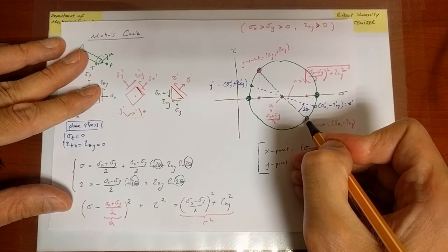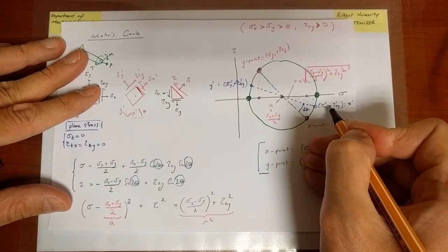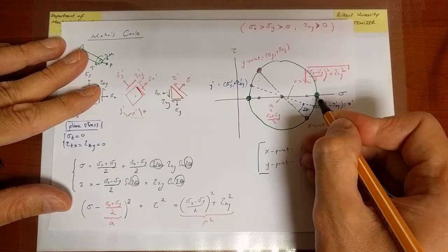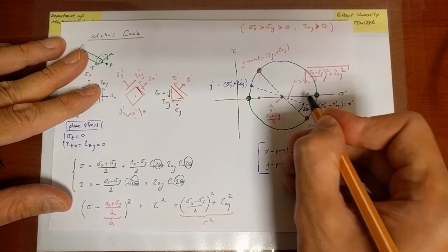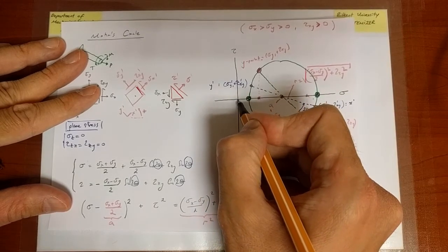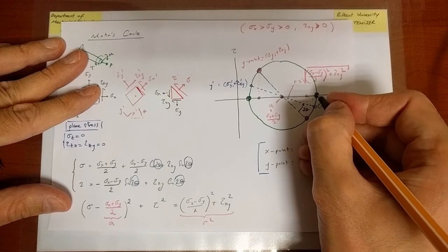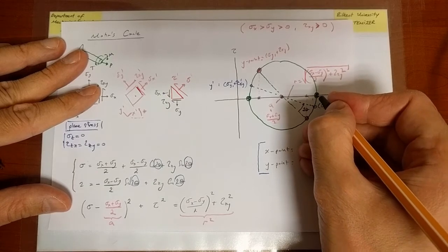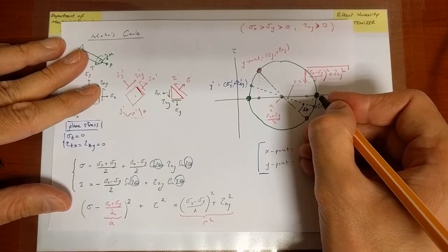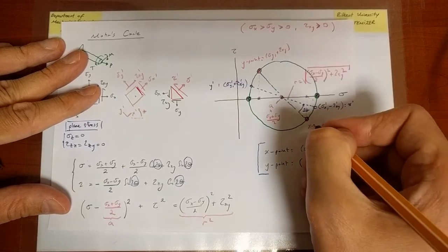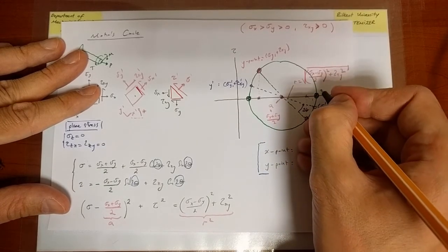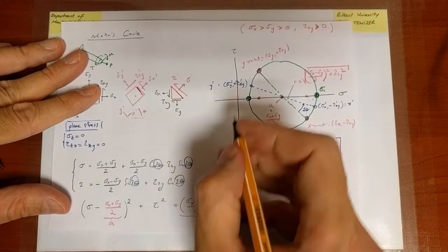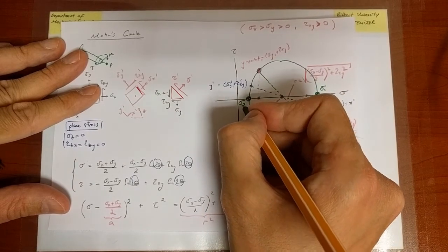So sigma x was sigma x prime with a certain shear stress, and now I've rotated so much that there is no shear stress. How do I know that? Well, I'm at tau equals 0. And so this must be a principal value, right? Principal normal value. And I'm going to rotate from x prime to sigma 1. That value is going to be sigma 2.